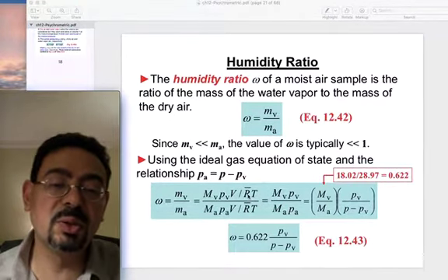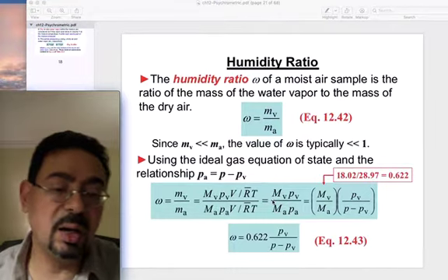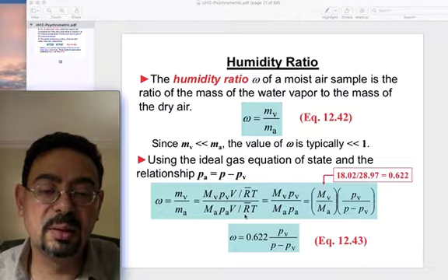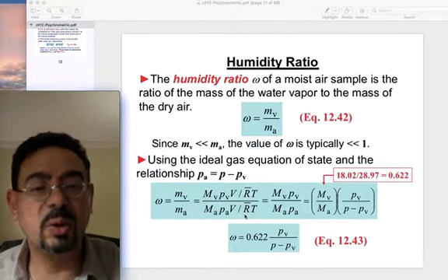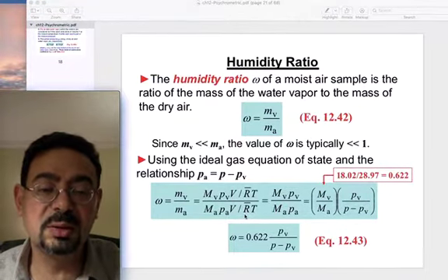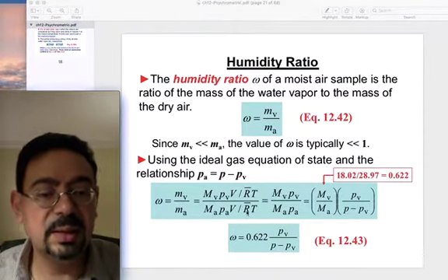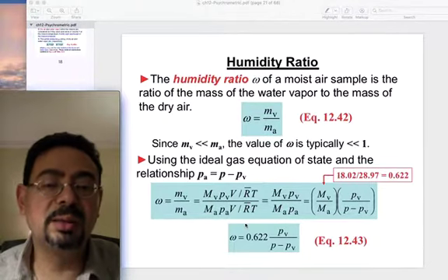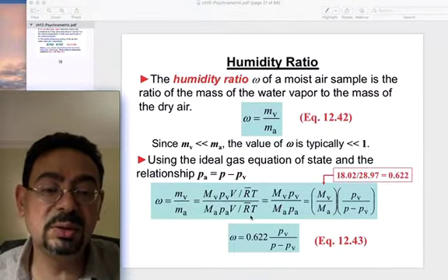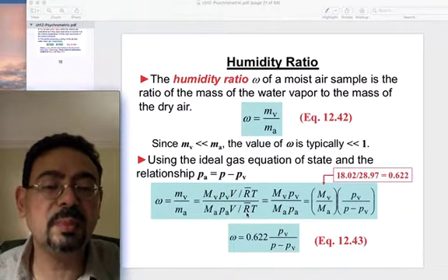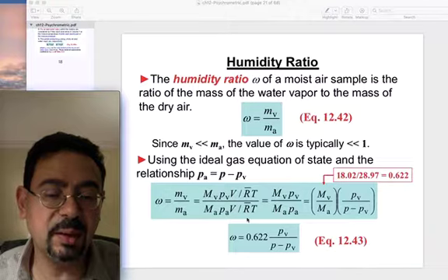That's R universal. So the R for a gas, for example, R here is 287, right? And for other things, we open a table and find out what the gas constant is and what the unit for R is: joule per kilogram Kelvin. This is not R. This is R bar, and some books write it R sub U, R universal. This R universal divided by M, the molecular weight, is R. So he is removing R, and instead he is writing R universal over M, which is the same thing, right?